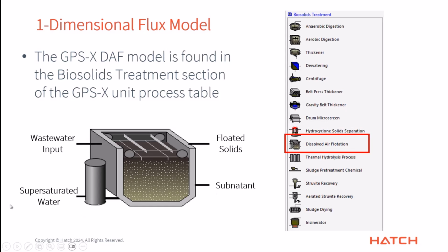I'll take a quick moment to mention that we do have this connection point over here, even though I'm not really going to be using it today. This connection point is for the supersaturated water that you would be theoretically adding. Our original version of the DAF model didn't have this, and it was just the 3 connection points. But we had a project where the amount of water being added to deliver the air that was going to be creating the bubbles was not an insignificant amount of water. So for water balancing reasons, we had to include it.